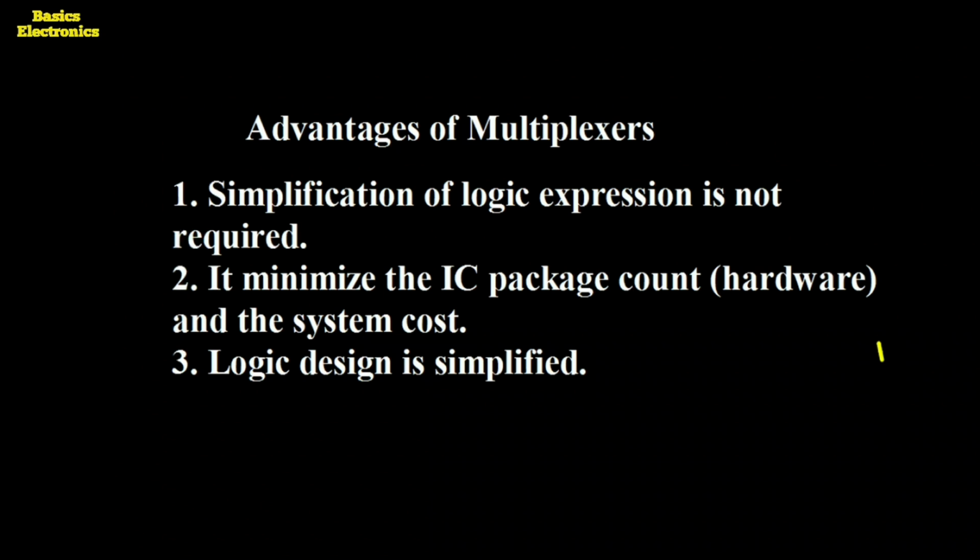The second advantage is that when we implement the logical expression, we do not need many types of logical ICs. For example, to implement the equation a bar b plus a b bar, if we construct the logic diagram, we need one OR gate, an AND gate, and a NOT gate.